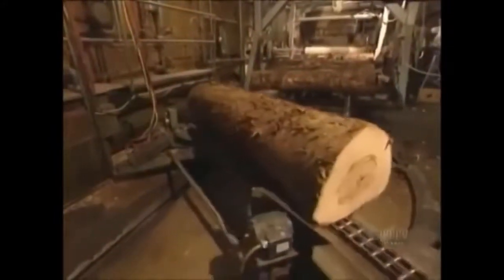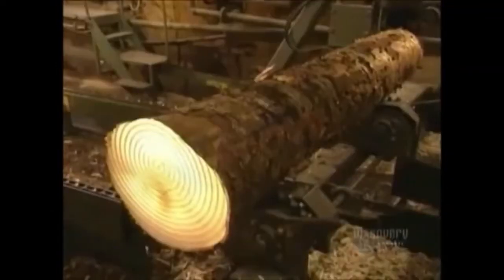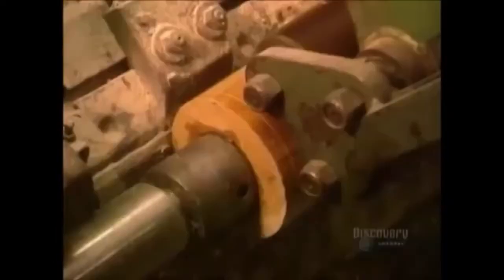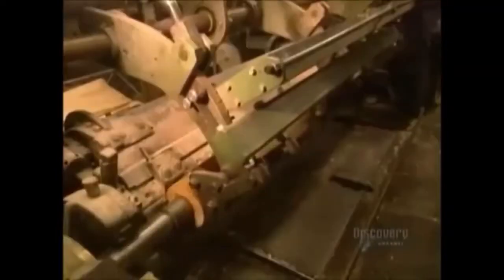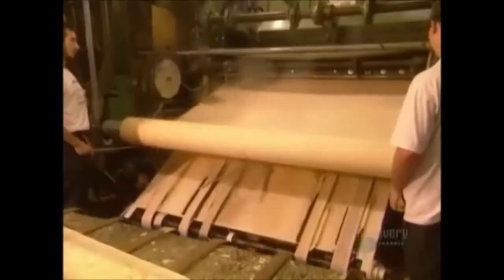Inside the factory, the steamed logs line up for the debarker, a machine that removes the bark. The operator projects concentric circles and uses a laser to carefully center the log on the debarker. Positioning is crucial for 2 reasons: so that as little wood as possible comes off with the bark, and to ensure the debarked log ends up perfectly cylindrical. That maximizes the amount of wood veneer a log will yield. The next step is called rotary cutting. As the log spins, a lathe skims off a sheet of wood veneer just 0.6 of a millimeter thick. The average log yields 134 linear meters of veneer.